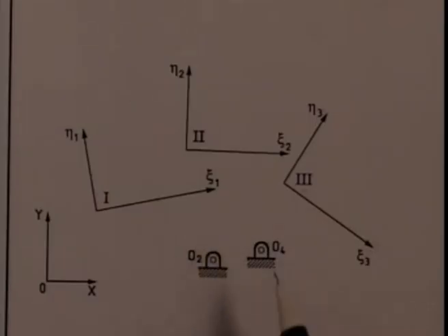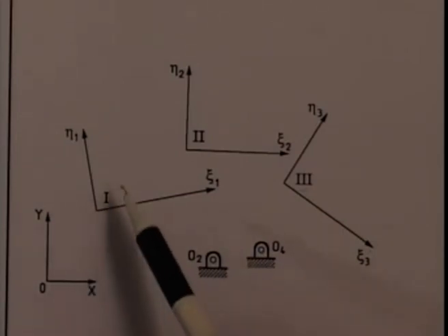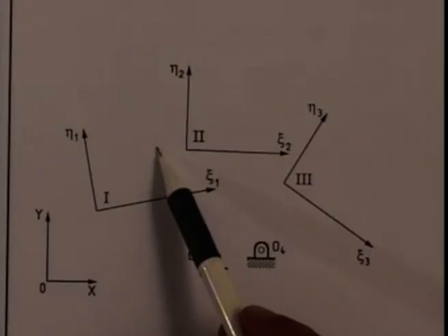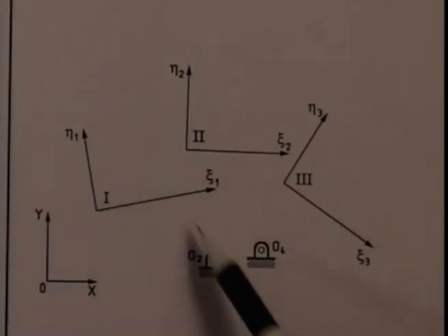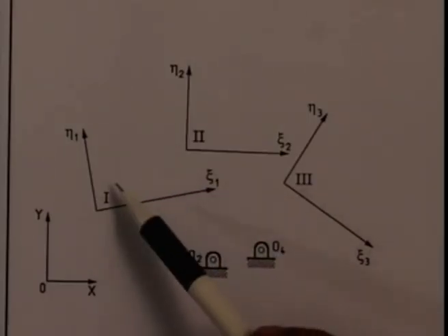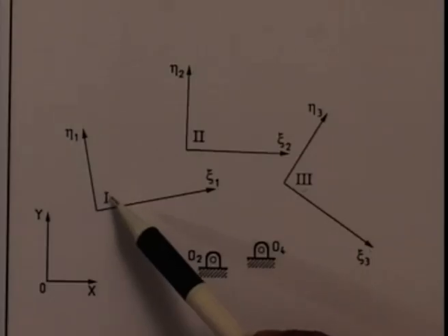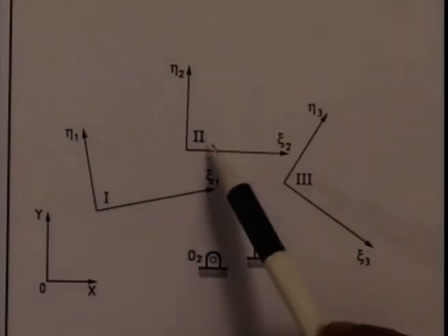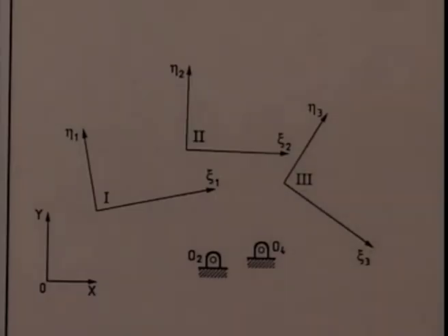The problem is that if we choose the locations of the fixed pivots at O2 and O4, where should A1, B1 be, that is the moving hinges in the first configuration, such that as we move this 4R linkage, the coupler moves from position 1 to 2 and then from 2 to 3.